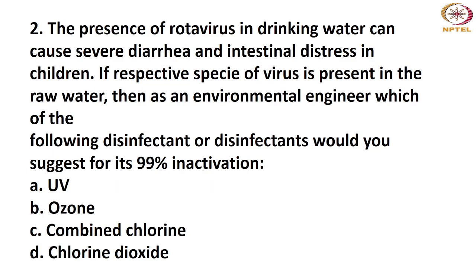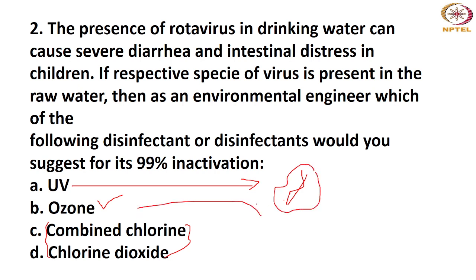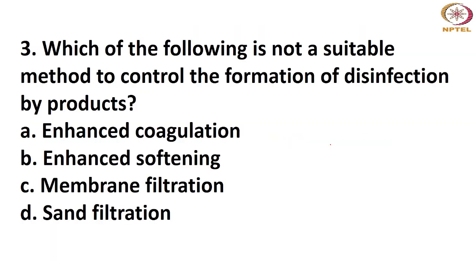One more thing to add, like here, you can see that chlorination will not completely remove this rotavirus. Ozonation is also not helpful, but if we can directly change their RNA structure, it can destroy it and eventually it will degrade. In case of ozonation, it can degrade only the outer surface. Maybe some of them will be present depending upon the dosage and the kinetics, but in case of UV, it can be completely destroyed or the inactivation will be around 99%.